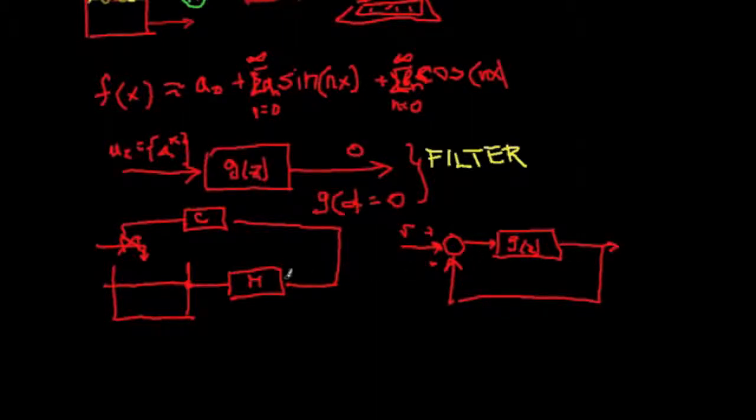Now, if we realize that due to this oscillation of the height here, we will also have a signal that oscillates, and it will be amplified by this simple controller and will amplify this actuator, that is the valve. We want to remove it, and what do we do? We will essentially just cut it here in this part and add a filter.